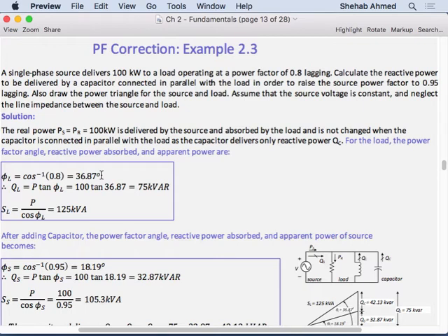And because we have P, the real power component, we were able to draw Q because it's perpendicular to P until it intersected with our trajectory for S. So we were able to do that. And you can do the same thing with the math from the trigonometry that we went through before as well, right? So Q in that case, the original Q, QL, was calculated as 75 kilovars, right?